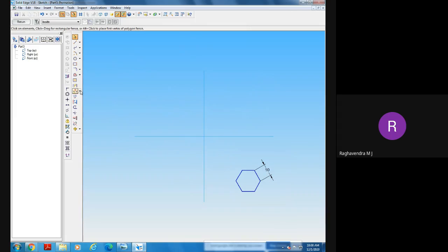Delete it. I need one of the drawing, but I need this one in corner position. Go to the line option, draw one diagonal to get the midpoint here. Now go to the move option. Pick the center. Are you able to see the center symbol here? Just move the cursor here, one symbol will appear, the center of this particular line. Now place the center exactly at the center of the planes.